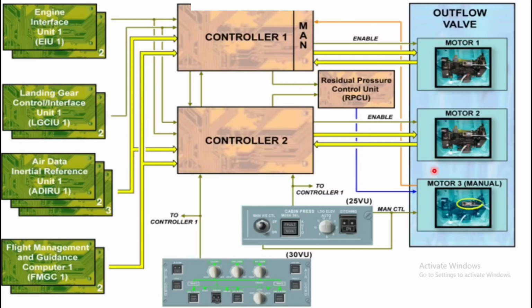In the cabin pressurization panel, you can already see the toggle switch, manual control, then field elevation. Automatically it will be in auto position, depending on the requirement. It can go for manual. Whenever you are going for manual operation, to identify the field elevation you should check the map or chart and just select that according to the requirement. And ditching I have already explained.